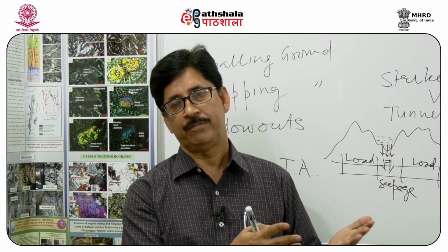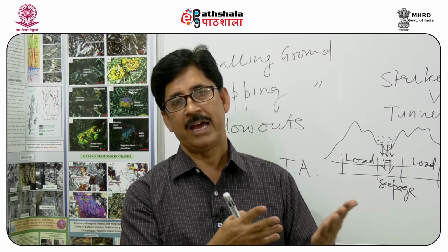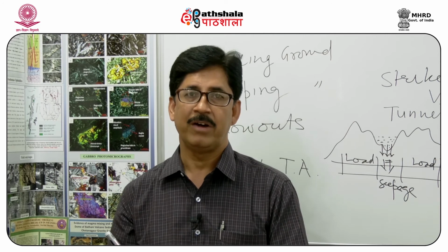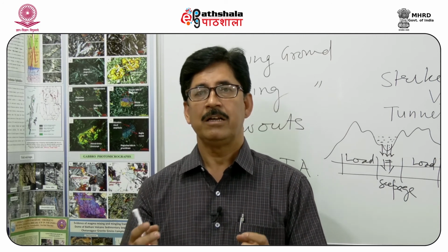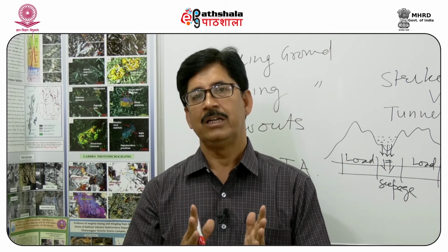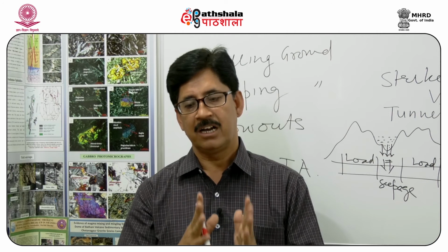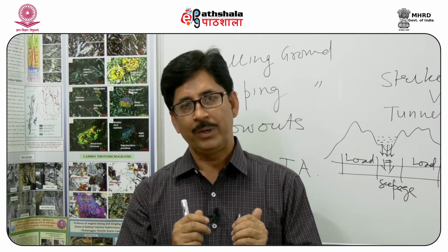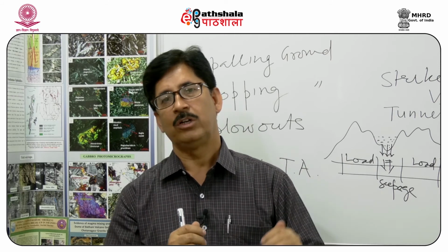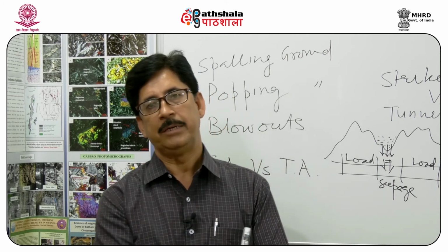So we may have rock bolts, steel arches, shotcrete, or fiber crete. What will be the thickness, the spacing, the length, all these can be calculated with the standard graphs which equate the rock mass quality with the equivalent dimension.